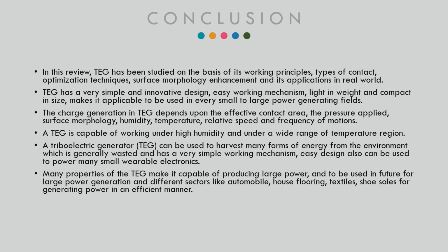As a conclusion, in this review, the triboelectric generator has been studied on the basis of its working principle, types of contact, optimization techniques, surface morphology enhancement, and its application in the real world. The triboelectric generator has a very simple and innovative design, an easy working mechanism, light weight, and compact size, making it applicable in every field from small to large power generation. The charge generated in a triboelectric generator depends upon the effective contact area, the pressure applied, surface morphology, humidity, temperature, relative speed, and frequency of motion.